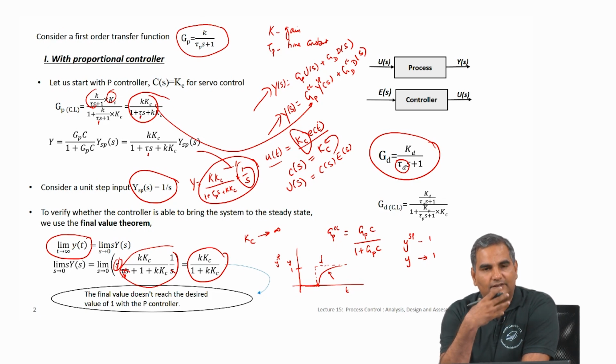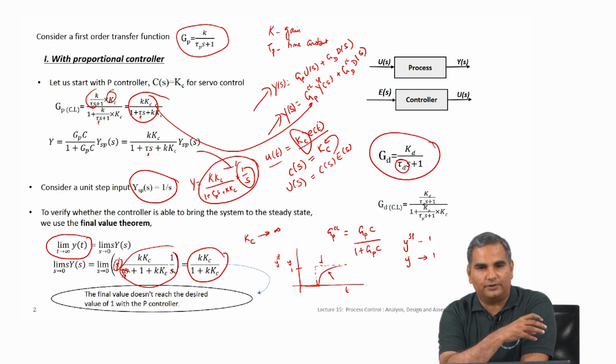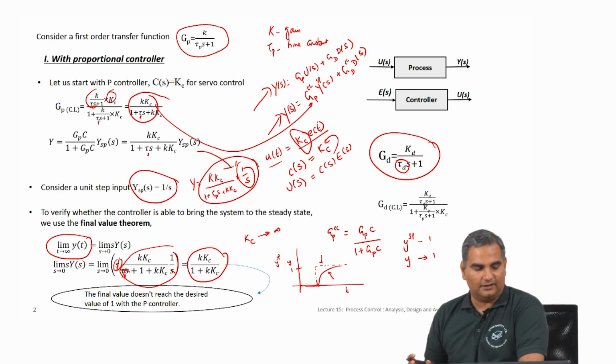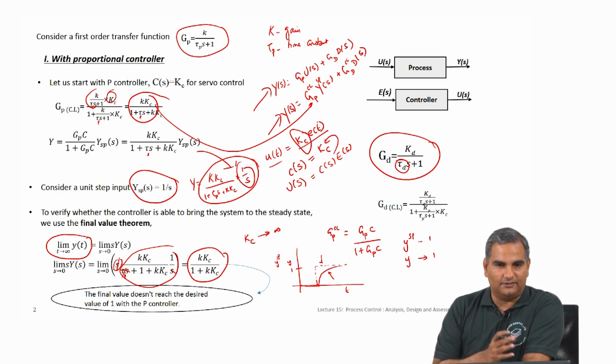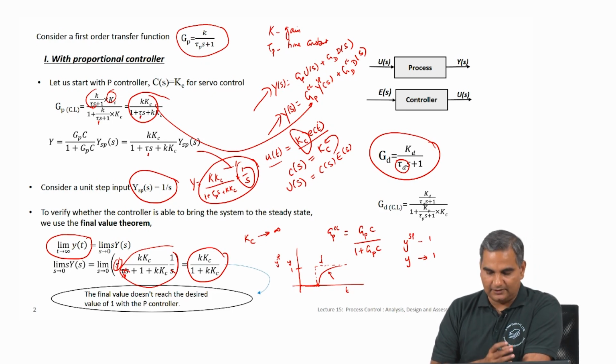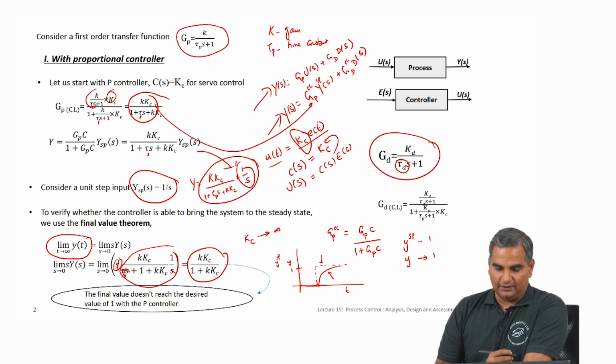So there are several useful properties of proportional control: ease of implementation, simplicity, does not introduce unnecessary oscillations. However, the negative is offset. So you will see in real plants several loops which are non-critical, but where you need simple control, you will see a proportional controller. Okay. So the advantages are rooted in its simplicity and ease of implementation, and the disadvantages in the offset.